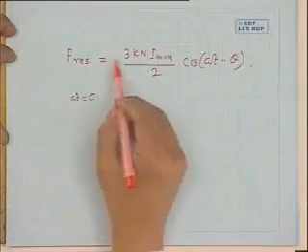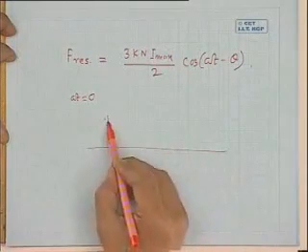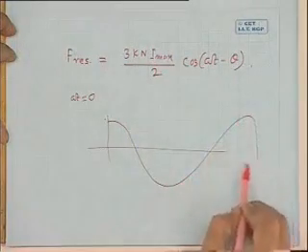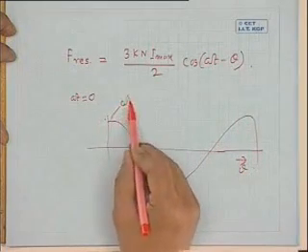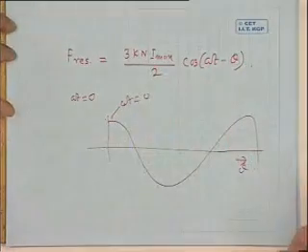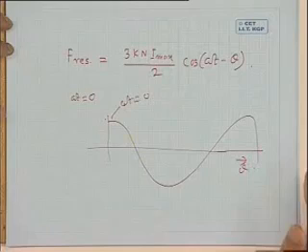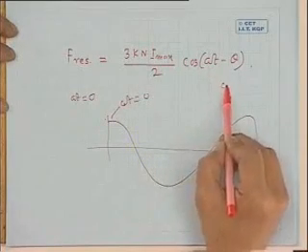What kind of resultant field is it? Is it a standing pulsating wave or is it something else? It is a traveling or rotating field. How? Because at omega t equal to 0, suppose you take a snapshot of this equation, how will it look with respect to theta? It will be distributed like this. This is the space angle, theta, at omega t equal to 0. What is the equation? Cosine minus theta, it is like this.